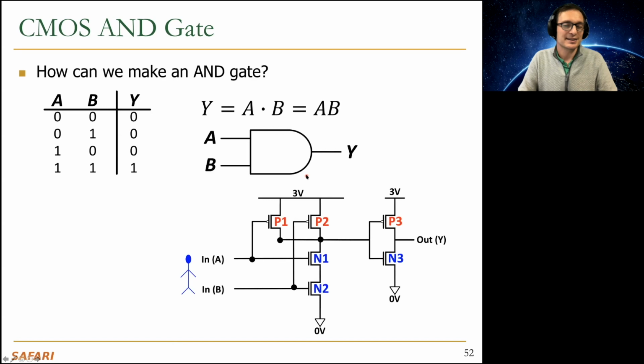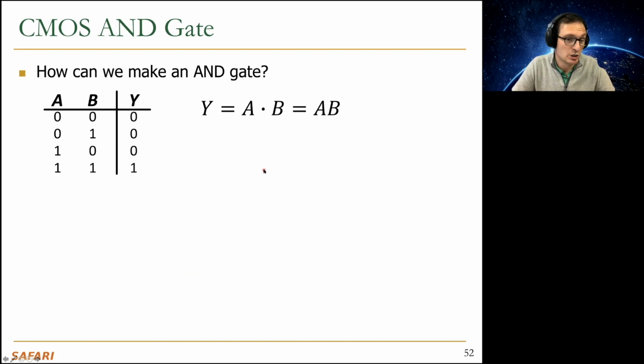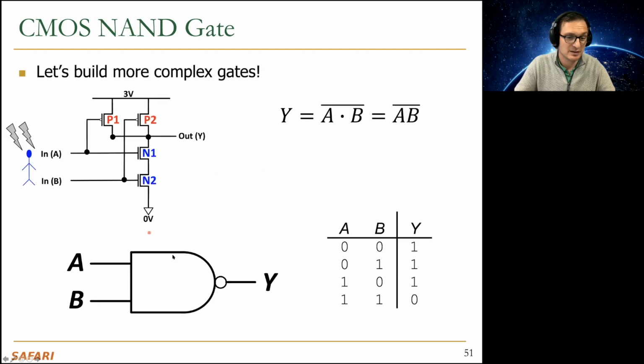But underneath, at the transistor level, this is the best way of building an AND in CMOS circuitry. We start with a NAND, right? The output over here is the NAND of A and B, and then we invert it. So even though this is the logic gate representation, another logic gate representation could be you start with a NAND and put an inverter after it, right? How do I draw over here? Let's see. Draw. Basically, this is what we've done.